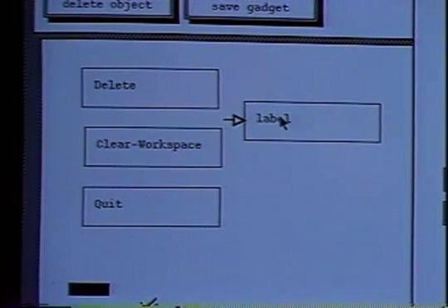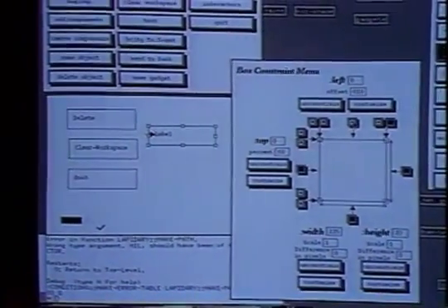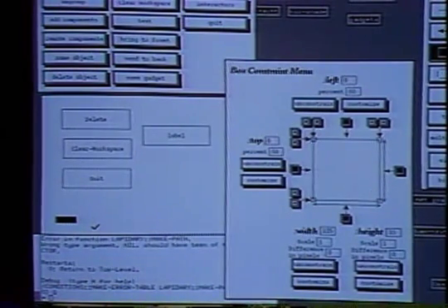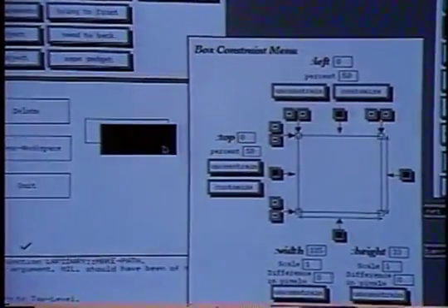The menu strings can be centered within the buttons using constraints. A constraint expresses a geometric relationship between two objects, such as centering. Constraints are automatically inherited by instances of a prototype. The button should appear to float above the display, so I will add a shadow to the prototype button.